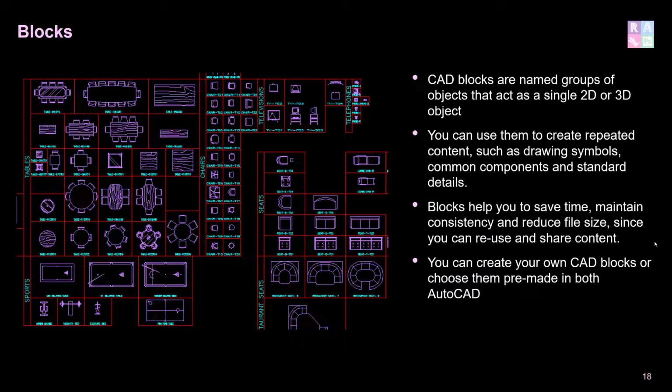Now let's say we're doing an office development and we want to lay these out. We have multiple conference rooms. That's hundreds, very quickly turning into thousands of individual lines that would need to be selected, copied, rotated, etc. So it's far easier to select them all and then block them, and then you're able to copy them around much easier. Even though they are made up of hundreds of individual lines, AutoCAD will just understand it basically as one object. So AutoCAD will run a lot smoother this way.